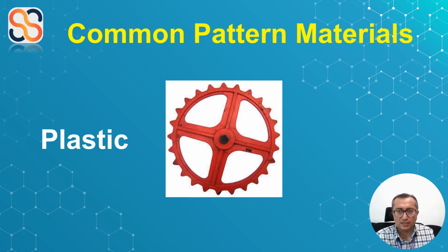To make a plastic pattern, we first create a mold in two halves using plaster based on a wooden model called a master pattern. Then we pour the phenolic resin into the mold and heat it, which makes it solidify into the final plastic pattern. Recently, foam plastic has also become popular. The most common type of expandable plastic is polystyrene, made from chemicals like benzene or ethyl benzene.